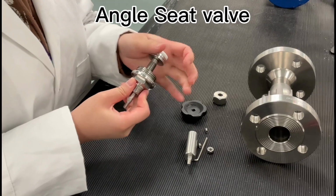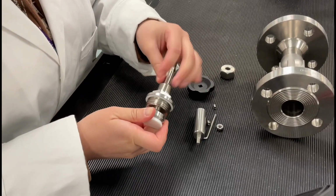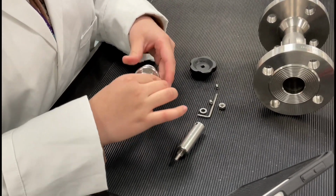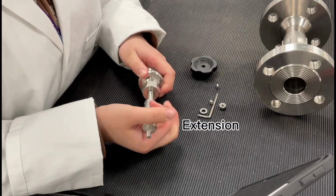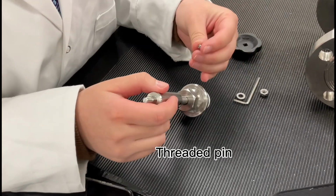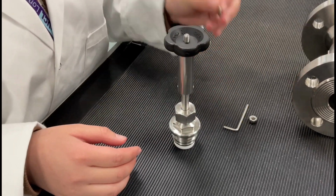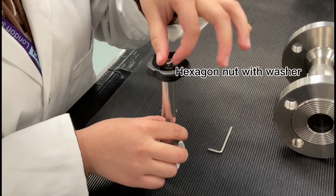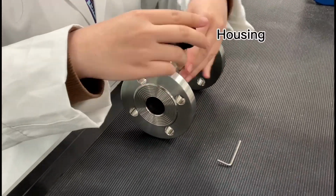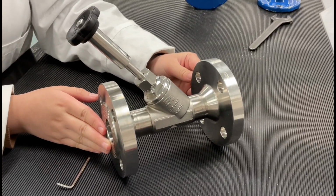In this video, we are going to demonstrate how the angle seat valve is assembled. Firstly, packing 3 small items to form the assembly unit 1, and connecting it with the item called extension. After that, screw 2 threaded pins into the unit. Put the hand wheel at the top of the unit followed by the washer and tighten with a nut. Lastly, screw the whole unit into the item called housing. This is how the angle seat valve looks like. We are going to show the centrifugal pump in the next video.